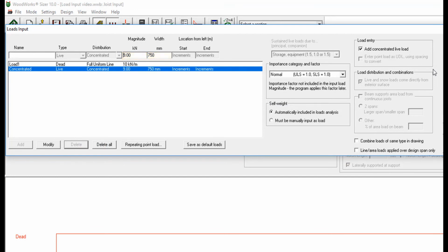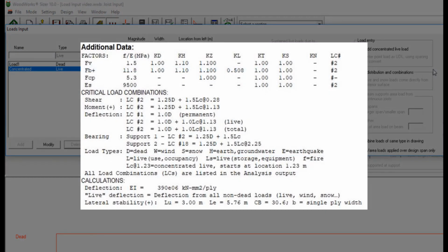When this option is applied to a beam, the program verifies all of the load combinations it ordinarily does, plus those with the concentrated live load. The extra combinations are comprised of the move-in concentrated live load combined with the other live loads present on the joist. Sizer determines the worst case for shear, bending, and deflection from all load combinations when performing the analysis. It will not perform separate analysis for concentrated and non-concentrated situations. You must run two separate designs for this.